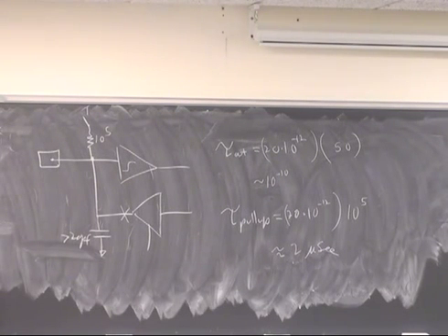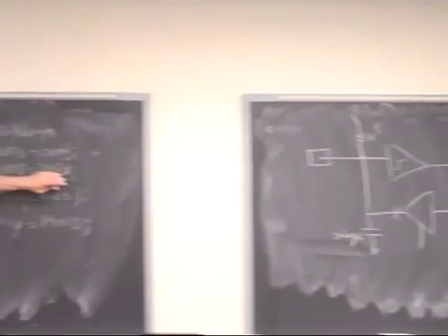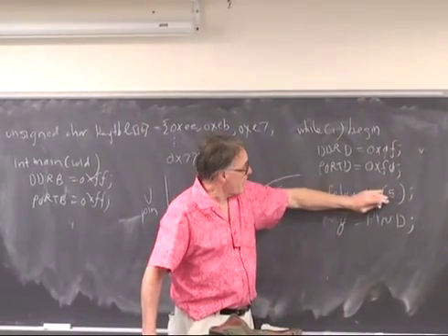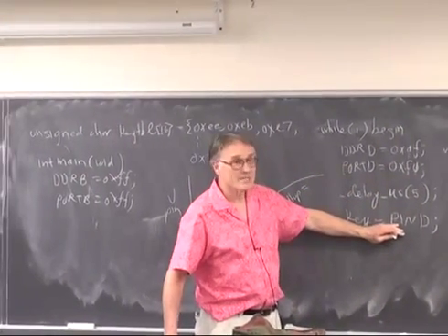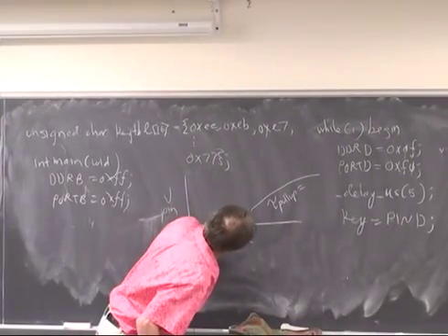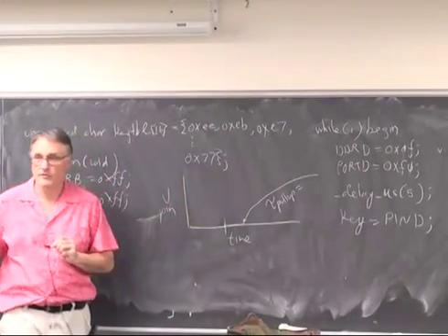So, if I just eliminated this, set these port pins to pull on the pull-up, when I read the key one cycle later, I would be right here on the charging curve.